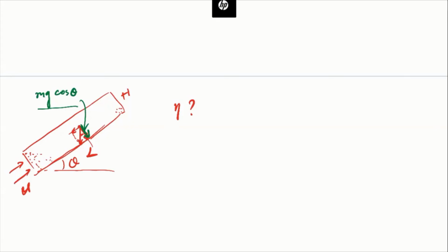The way we do that is just equating mg cosine theta with the drag force, that's 3 pi mu dp divided by c multiplied by Vr. Or we can just use the v here, mainly because the flue gas or the ambient environment doesn't have a vertical velocity. Okay, so this v here is just the settling velocity.